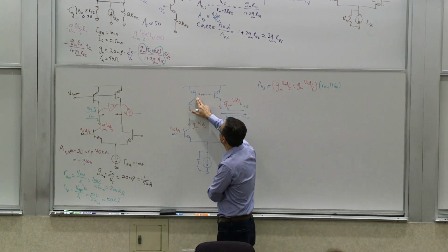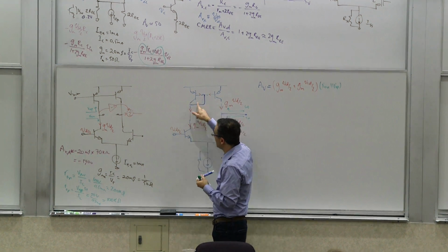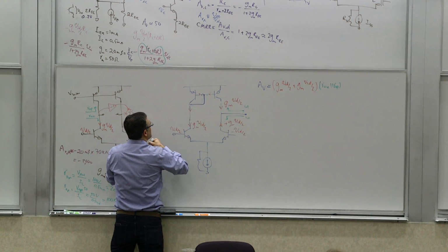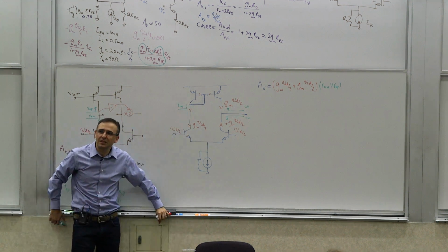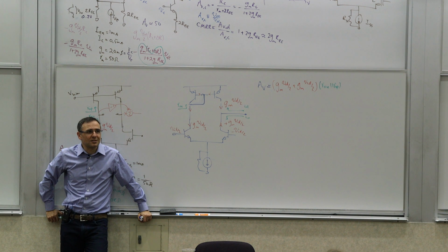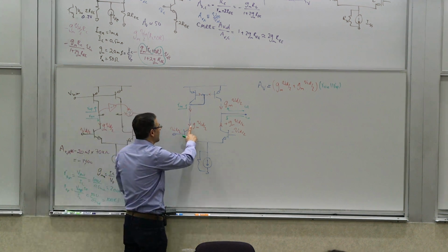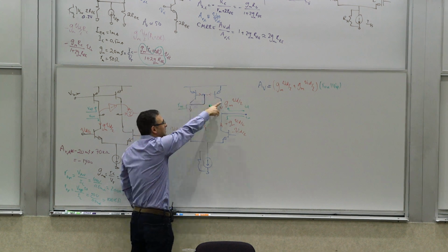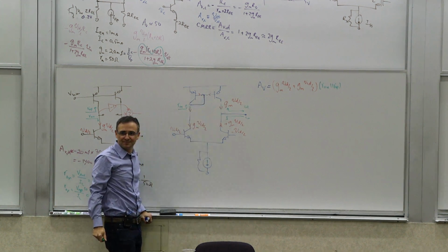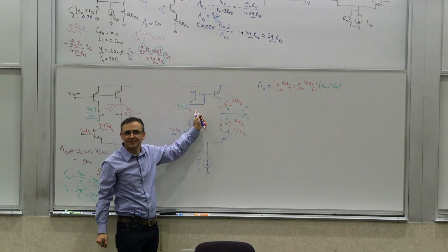So that cannot happen on that side. This current needs to be provided somewhere where you don't care about the impedance, which is on this side. Now what you're creating here is that by looking into here, you see basically RM. You're making what kind of a meter? A good meter for what? For currents or voltages? You're making a good current meter. You're making a good ammeter here. Because that's what basically sucks all of this current straight into itself. And then it reflects it here. So that's basically your inversion here. Yes?